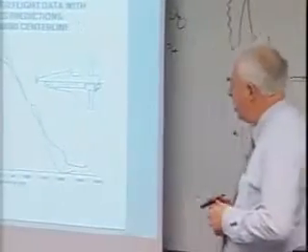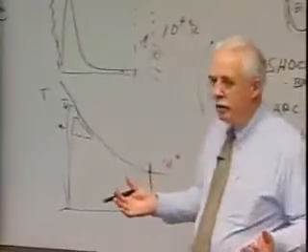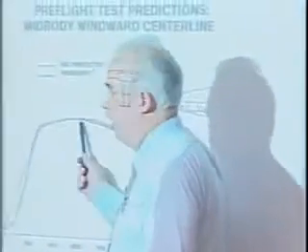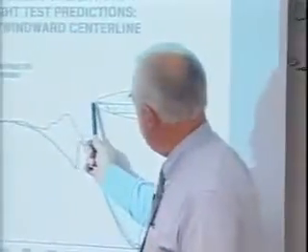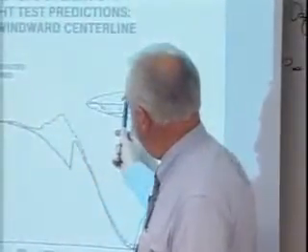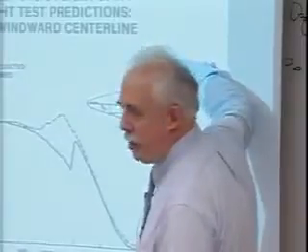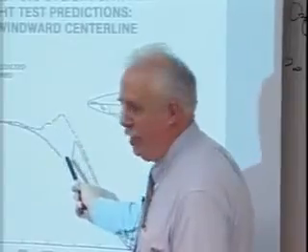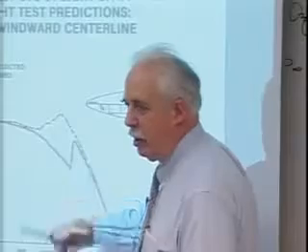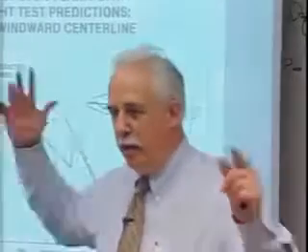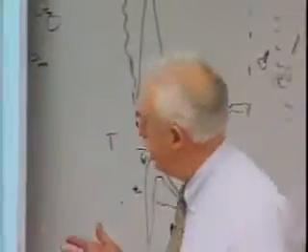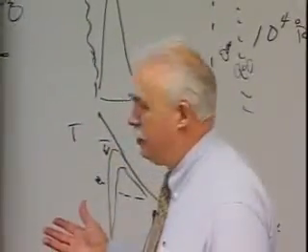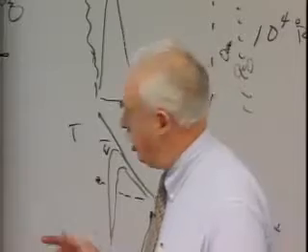Okay, why don't we go to mid-body now? All right, here's something you might see in a journal. Right where we wanted it, and that's where we had the most confidence too. We got away from the subsonic, supersonic condition. We were into a marching solution. That's as good as we could do it those days. Okay, and we knew that transition was going to be later than what we predicted, because wind tunnels are noisy. You got walls, you got all kinds of reflected noise, and wind tunnels are notoriously conservative relative to boundary layer transition. But amazingly,